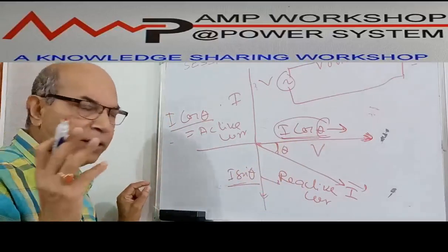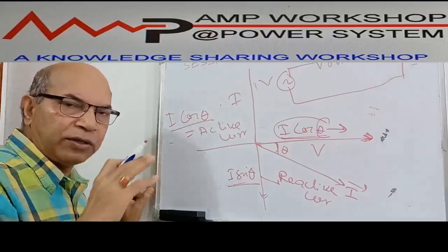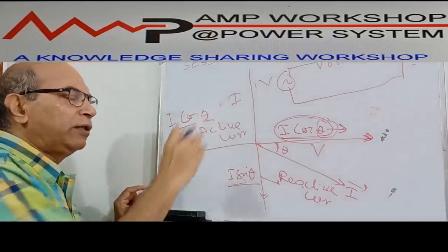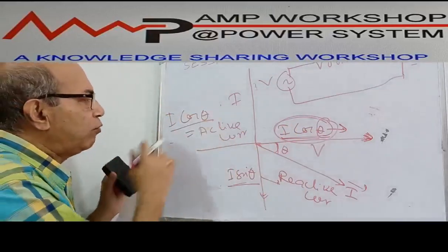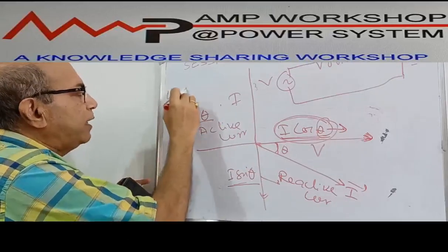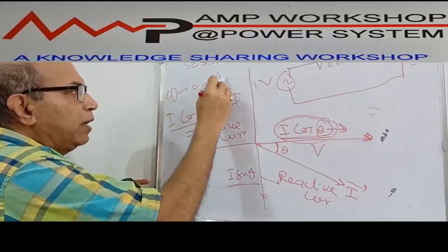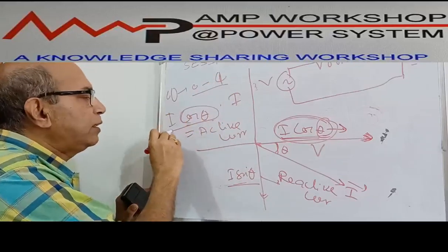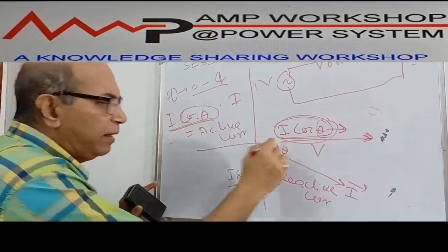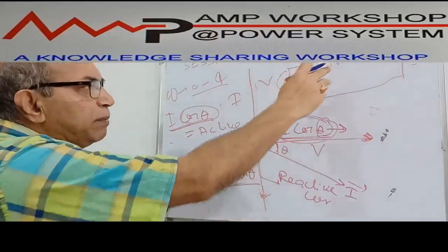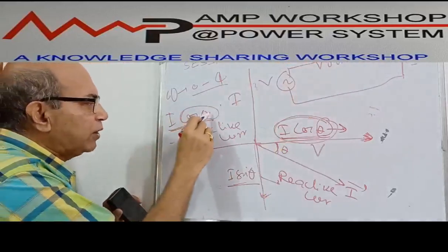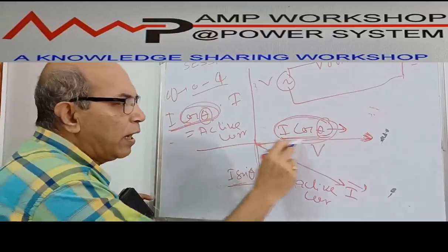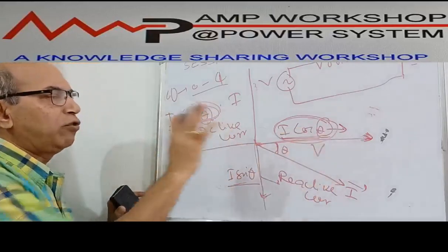We can understand from this that the phase angle, lagging or leading between the current and voltage, which we have seen in the waveform, has an immense impact on the active current. We know cos theta varies from 0 to 1. If cos theta equals 0, the active power becomes 0, meaning the current is perpendicular and the circuit is purely reactive. But if cos theta equals 1, when theta equals 0, the current and voltage are in the same phase.